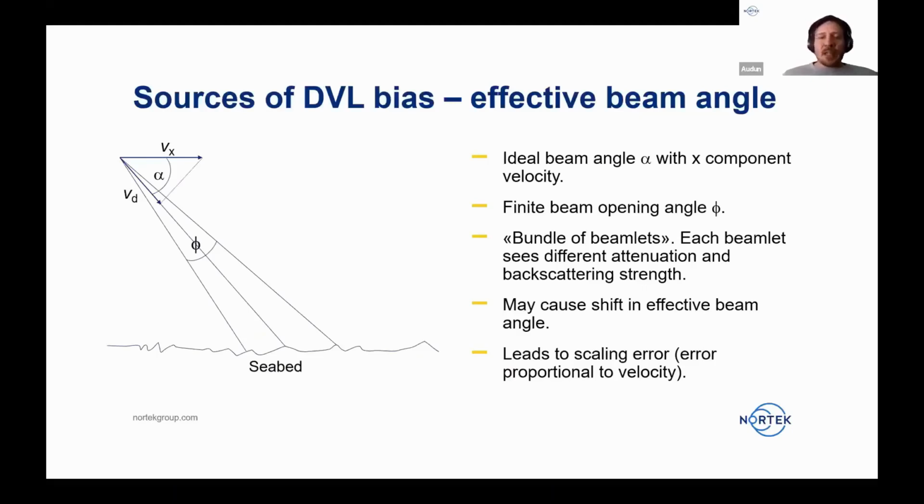Then if I could do the calibration first in situ, right, in this particular field, where I know that the bottom's not going to change that much. And also if I can do it at the actual altitude I'm going to operate, and with the same water parameters that I'm going to operate at, that's obviously going to give me the best result. Because if I take it somewhere else, my calibration is going to be slightly off at least.